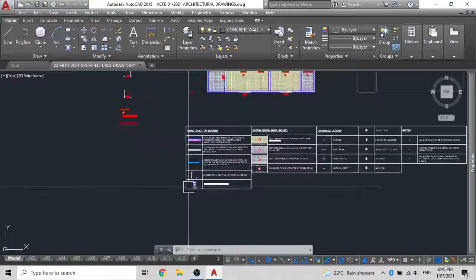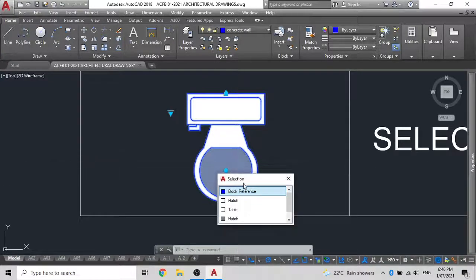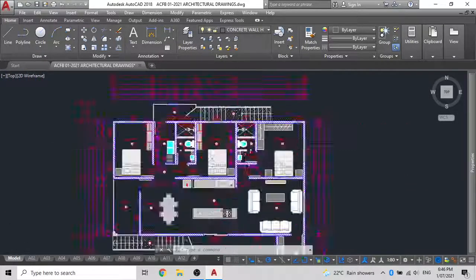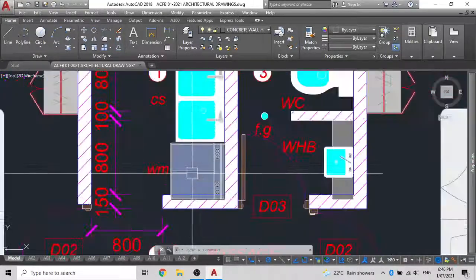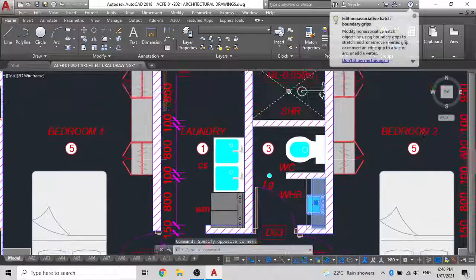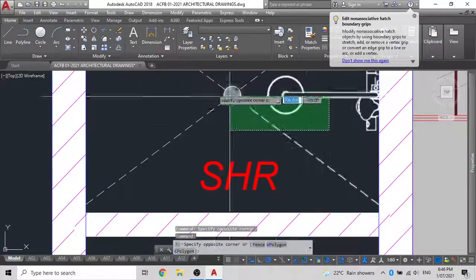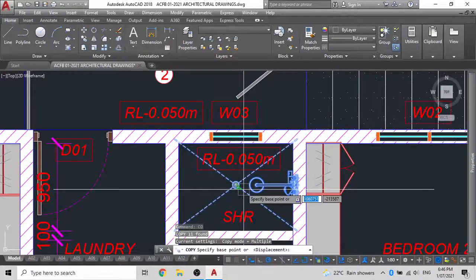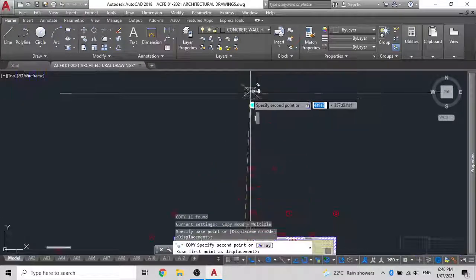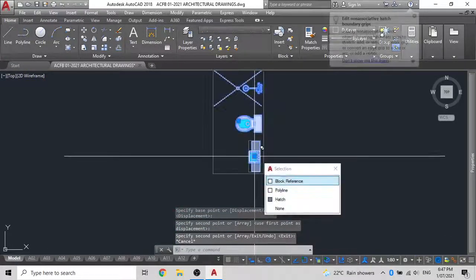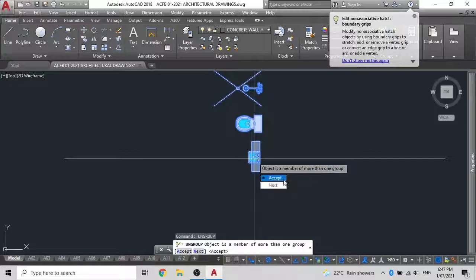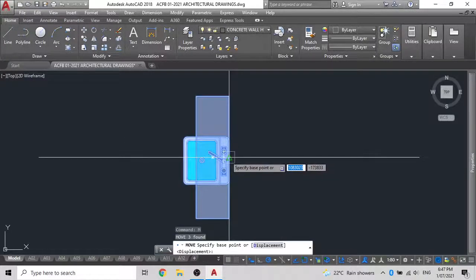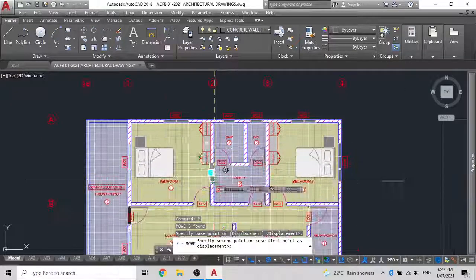Now what we can do is simply insert our washroom in the wet area layouts. So we'll just go to my reference drawing over here and we'll start to bring in all these things that are important. Group them so that you don't have several lines to deal with all the time. Paste them up there, then ungroup them. And just move all these cabinets and their benches to wherever you prefer.